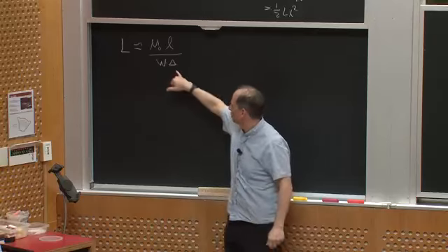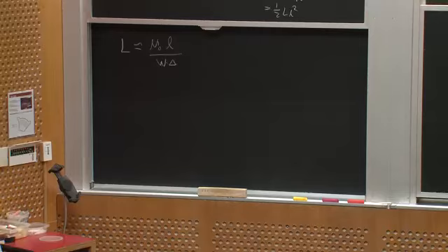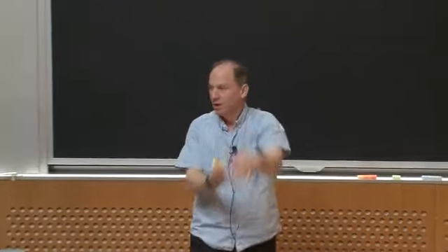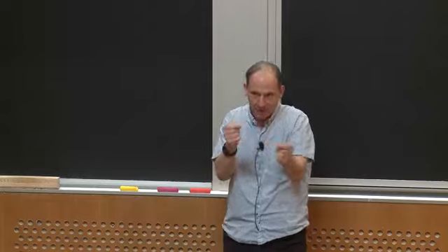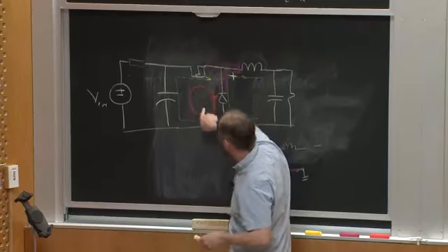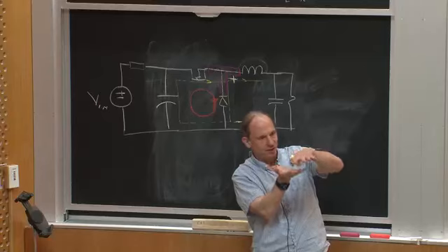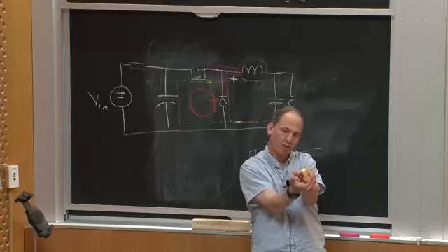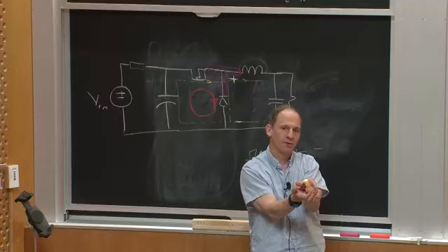And then the other thing I can see is here, I want delta to be small, right? So if I'm going to carry current out and return it, I want the spacing between those traces to be really low. Okay? So the thing I'm thinking about when I'm thinking about what I'm going to make this interconnect loop do, it's not only that I can imagine this original thing I drew and say, yeah, I want this loop to be tight, but this might actually be in multiple dimensions that I have to think about. And if I have to carry current over some distance, carrying a wider trace and putting those traces closer together helps me make that inductance low. Okay. Any questions about that?